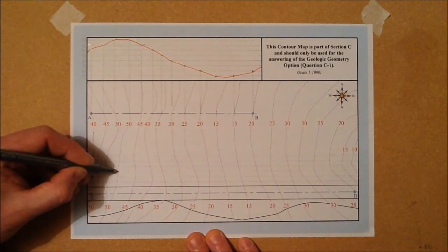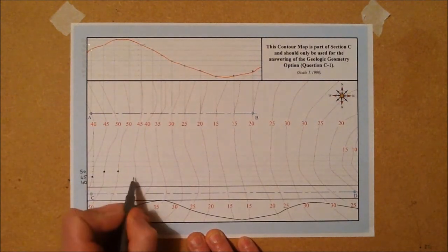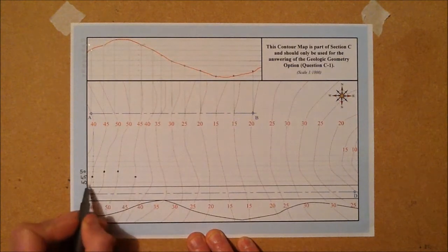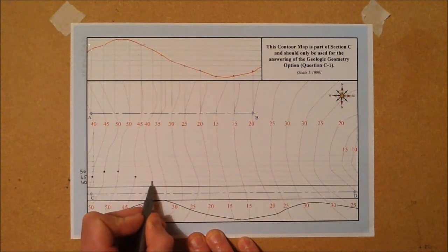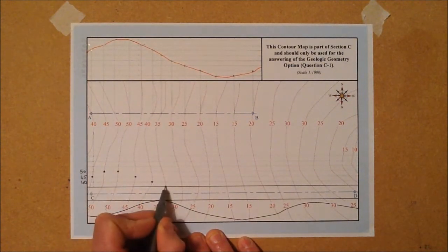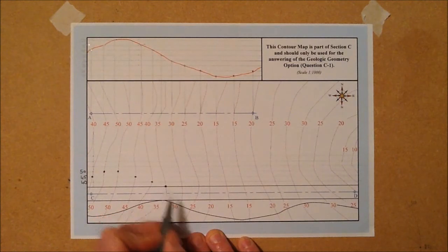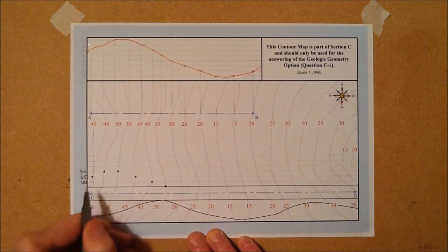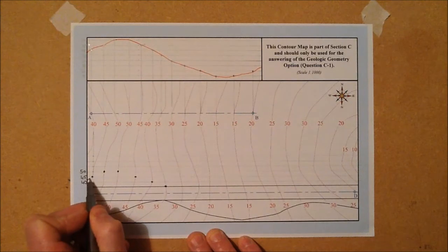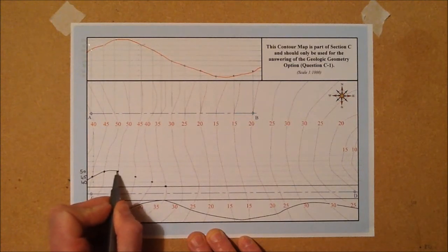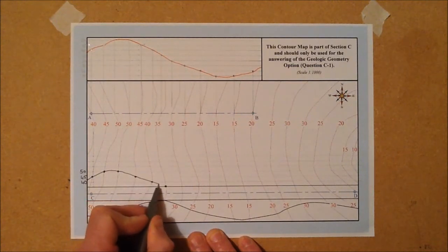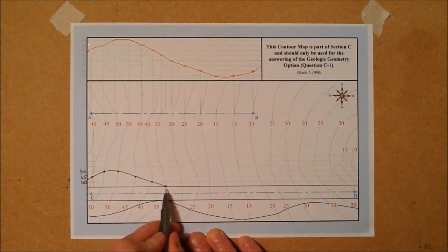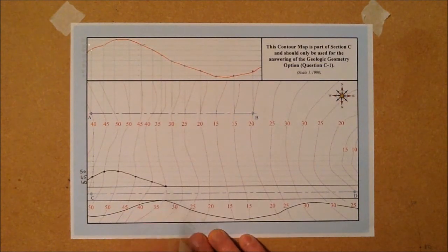Again, the next contour line is 50. We're going down again to 45, again across to 40, and this last one here is 35, which is actually the level of the road. So basically you carry on through those points and draw in your curve as you see here. Where I come back to meet the level of the road is at 35 meters of altitude.